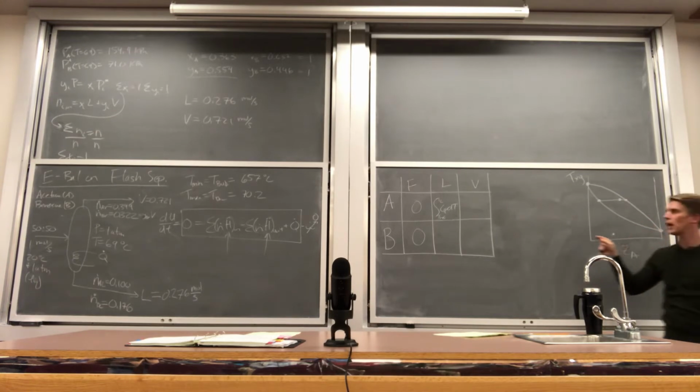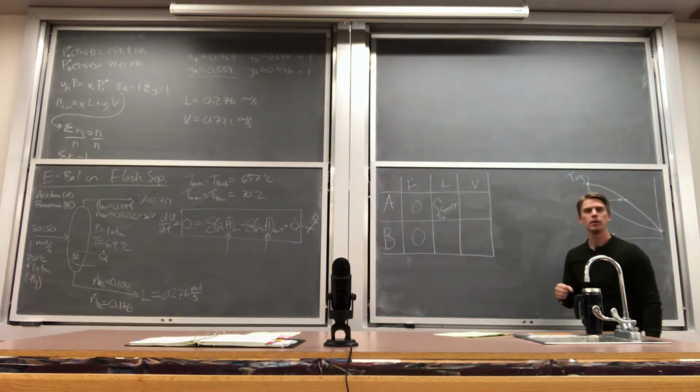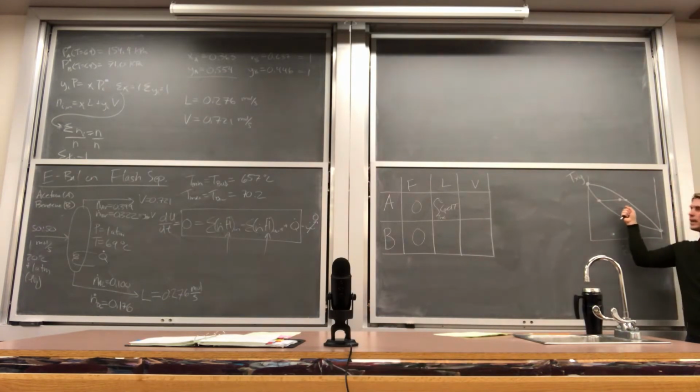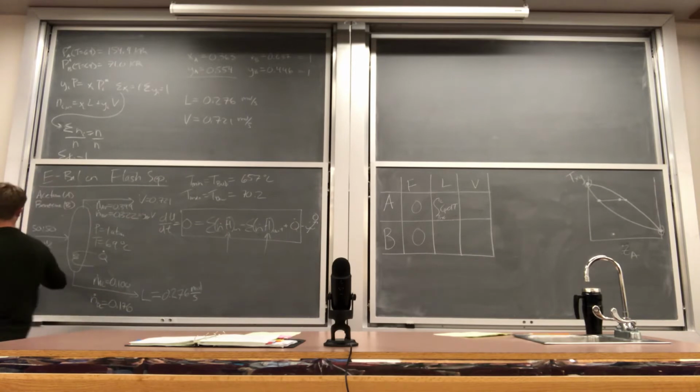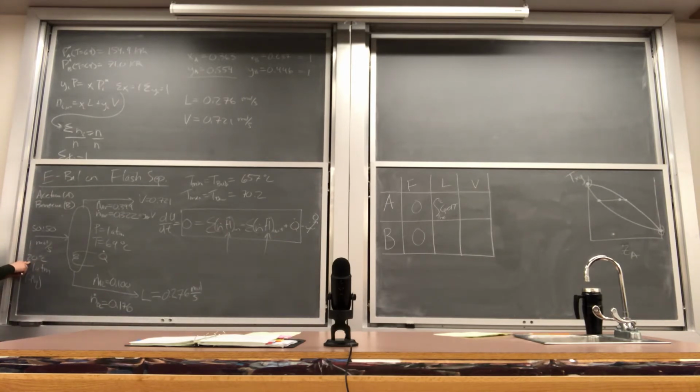So you always have to go through this process now of dealing with the vapor enthalpy, choosing a path that goes through known conditions. So what we could choose to do is, we're starting off at 20 degrees C. We could choose a path of heating the fluid up to its normal boiling point, boiling it, and then changing the temperature to get down to the outlet conditions there. That's one path that we could choose. And in fact, if you choose the reference state as 20 degrees C in liquid, that's the path you would likely have to choose.